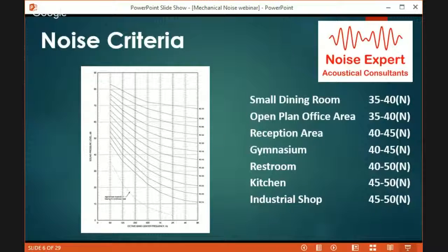The dBA noise level is just the sum. It's logarithmic levels, but it's the sum of the levels in the different octave bands weighted for how the human ear perceives noise. Not all noise is perceived equally. So they came up with this A-weighted level, since we're more tolerant of low frequency, like diesel, low frequency engine noise, than we are of whistling, a high frequency above 1,000 hertz.